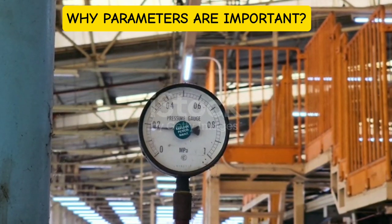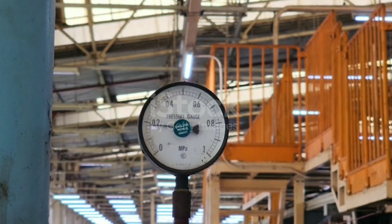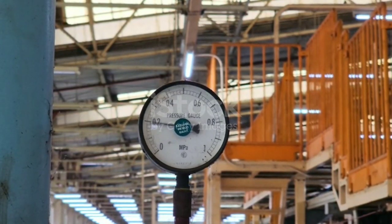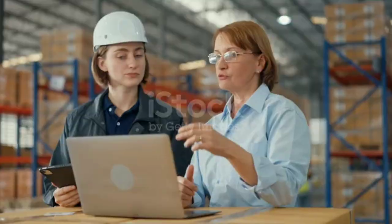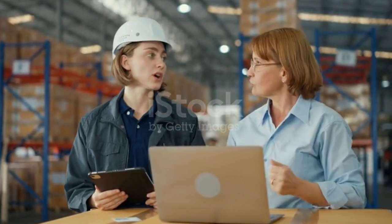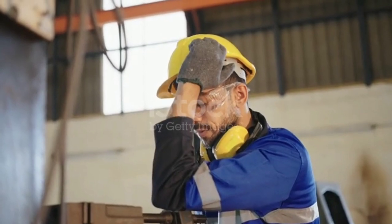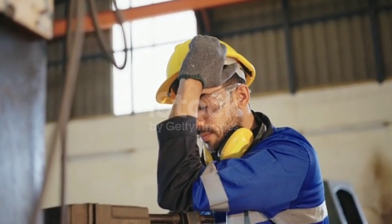Having the right parameters defined allows your HAZOP team to systematically analyze what could go wrong and determine what impacts those deviations could have on safety, quality, and operation. If parameters are ignored or poorly defined, the analysis could miss critical risks.